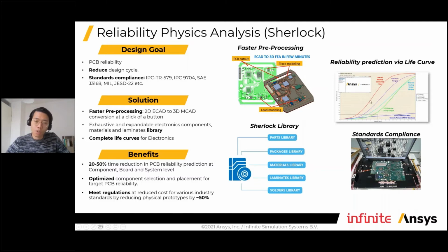We have vibrations, we have thermal cycles, and also different parts, different combinations, soldering techniques, and how we package our chips on top of the PCB boards. All these factors come together, and it's inherently very complicated.